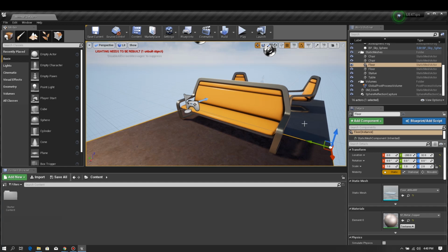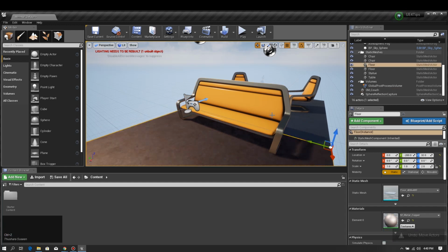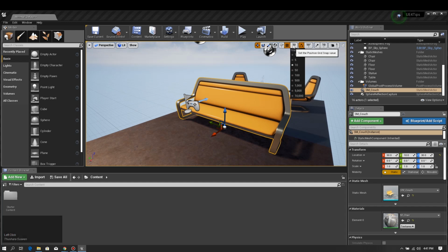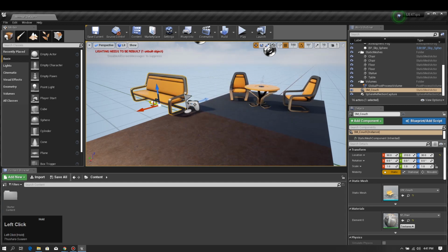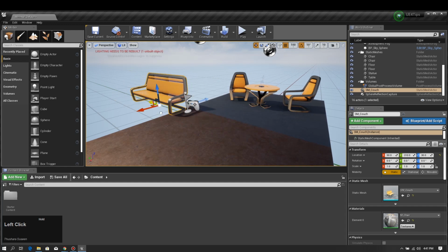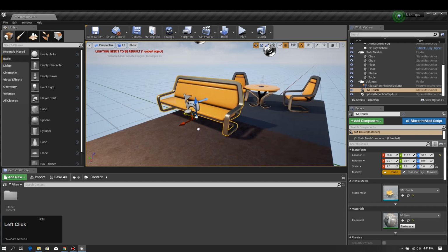Okay, so there's another interesting part that we need to look into. This is the feature that you have inside Unreal to snap your object movements into a grid. So if you increase this transform location snapping to 100, you can only move this object in units of 100, so you can see it snap to the grid. Even if we move our mouse, it doesn't move, but after it goes beyond the grid size, it will move.